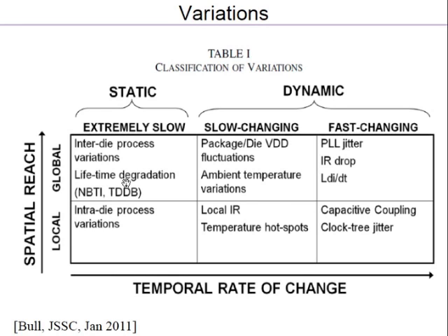Mainly the threshold voltage changes because of some changes in the oxide, above the gate oxide, above the channel. You can also have slow changes in VDD, maybe. Ambient temperature, of course: you are operating here in the room, it starts heating up; when you go out, it's cooler, and so on. And again, you can have global changes and local changes. Global changes are changes which affect the whole chip. Local changes are changes which affect portions of the chip.